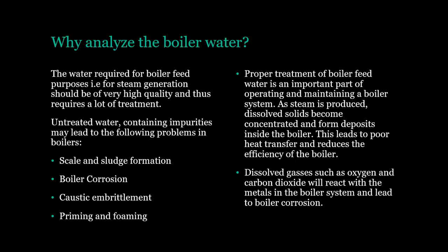As steam is produced, dissolved solids become concentrated and form deposits inside the boiler. This leads to poor heat transfer and reduces the efficiency of the boiler. Dissolved gases such as oxygen and carbon dioxide will react with the metals in the boiler system and lead to boiler corrosion.